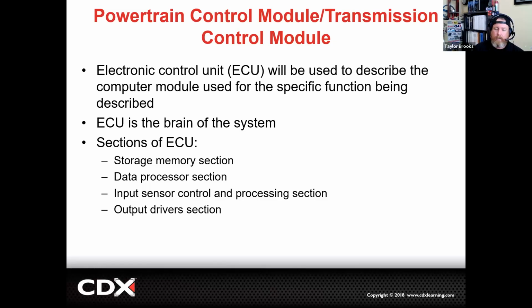Short-term memory is usually 120 seconds, and that's going to be 60 seconds before an event occurs and 60 seconds after an event occurs. And then there will be long-term memory that will be stored and sometimes indefinite. When we start to get to permanent diagnostic codes on modern vehicles, some of those systems can store information for the life of the computer with or without voltage.